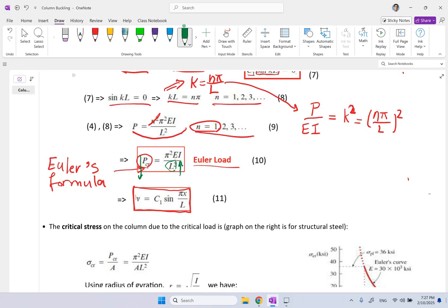On the other hand, you see the material. The stronger the material, of course, the stronger the critical load. And then I depends on the thickness of the beam and the height of the beam. So the bigger the I, the bigger the cross section, the bigger the critical load. And the more slender it is, which means I is small, in a linear manner, P is going to go down.